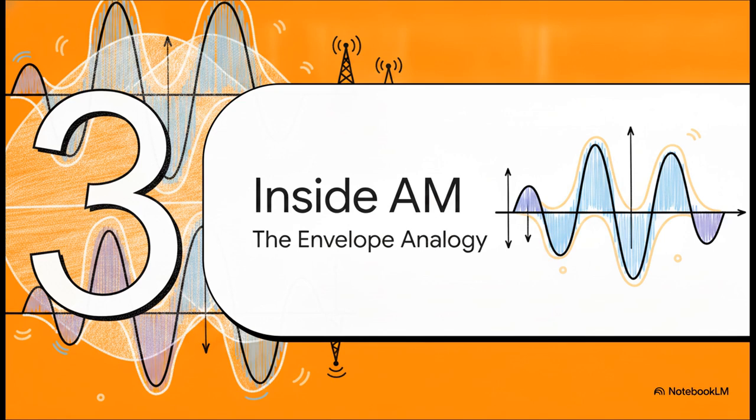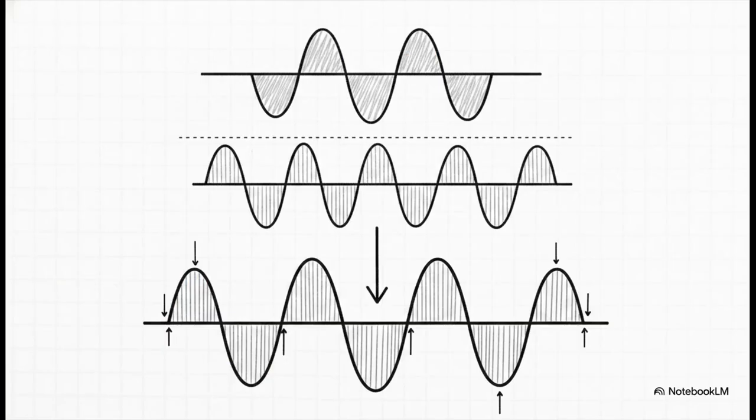Section 3, inside amplitude modulation, the envelope analogy. So amplitude modulation, or AM for short, is the process of changing the amplitude of a high-frequency carrier signal so it perfectly matches the modulating signal, the actual information. In the real world, this typically operates in the band between 535 and 1600 kilohertz.